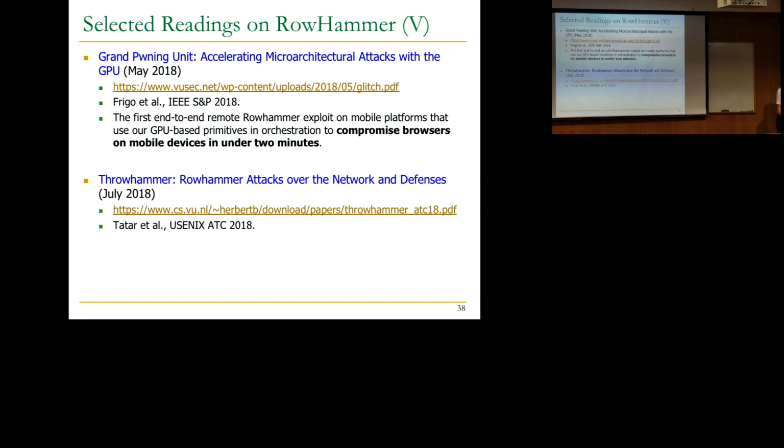Specifically, do you have to get lucky, or is it something methodological that in the end will break it if you do it long enough? Well, I think if you do it long enough, you'll break it, yes. The attack itself is probabilistic, so if you have a limited amount of time, you may not get lucky, but if you do it long enough, you will eventually gain. On any DRAM chip? Not on any DRAM chip, no. The DRAM chip needs to be vulnerable. But you said 80% of them are. Exactly, that's right. According to our results, it's 80%.